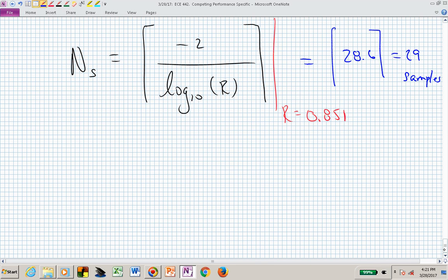And if you remember, we wanted a settling time of 1/2 of a second, or 500 milliseconds, and that corresponded to 50 samples. Now, for this new collection of parameters with an r value of 0.851 and an angle theta sub d equal to 0.314, we have a settling time, t settle, that's n sub s times T, which is now 290 milliseconds, or 0.29 seconds.